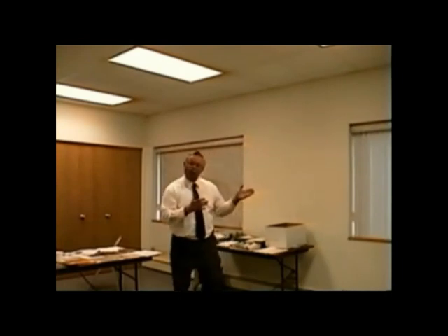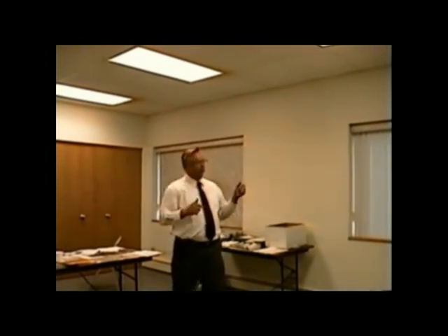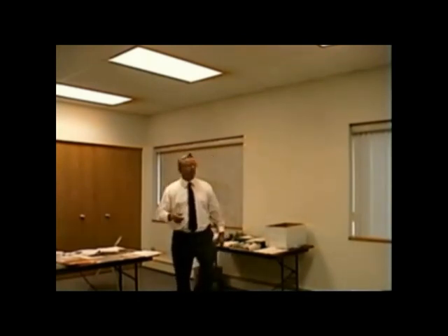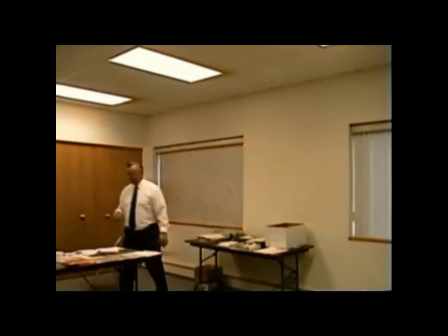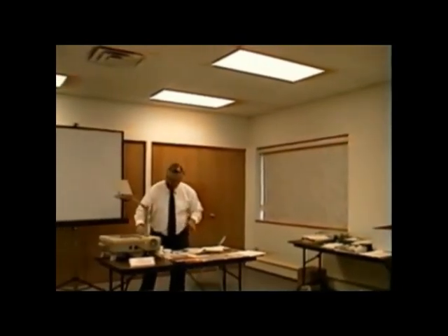I have to tell you, we had a contractor where we did a live class for him, and we actually had him check the heat anticipation. And he says, well, no wonder I'm having trouble with all of these mechanical thermostats. He says, I know that they all come preset at 0.4, and I know that you said it was supposed to be 0.1, and now I see on the amp meter, it is 0.1. He says, but I was turning them all up to 1. See, there's a big difference from 0.1 to 1, and he kept warranting the thermostats. And they still didn't work, so he went to electronic ones, and they worked fine. So at that point, now we understand about the low amperage for heat anticipation, okay? All right.